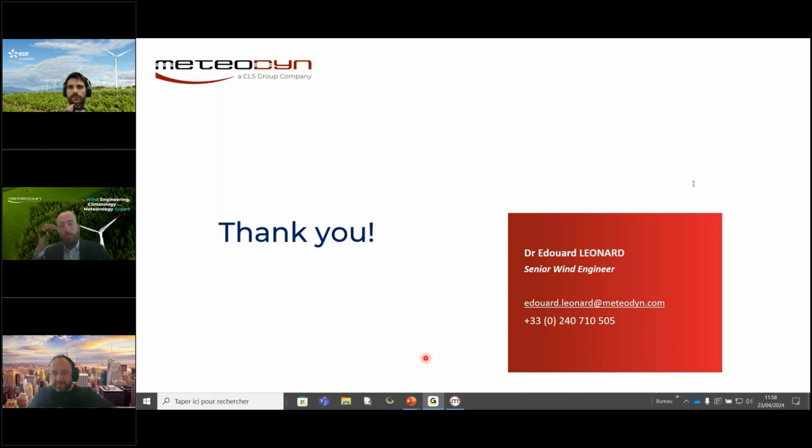One interesting question was how to determine the ratio. The starting point is the height of the trees, because this is something we know from the site. With this project, Aurélien, you had some estimation of the height of the trees. So the first parameter to adapt is the ratio. If you know the roughness length and the ratio, you can easily deduce the real height of the forest. And then the forest density is the adjustable parameter.